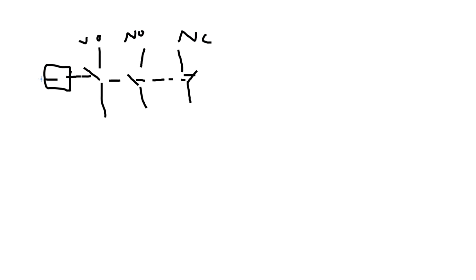These switches can also be paired together. For example, in the diagram that I'm drawing for you now, here we have three switches. Two of them are NO and one of them is NC. And all of these are coupled together so that when you actuate the switch, all of them will change their state simultaneously, and the NO will become forced closed and the NC will become forced open. So something to keep in mind.